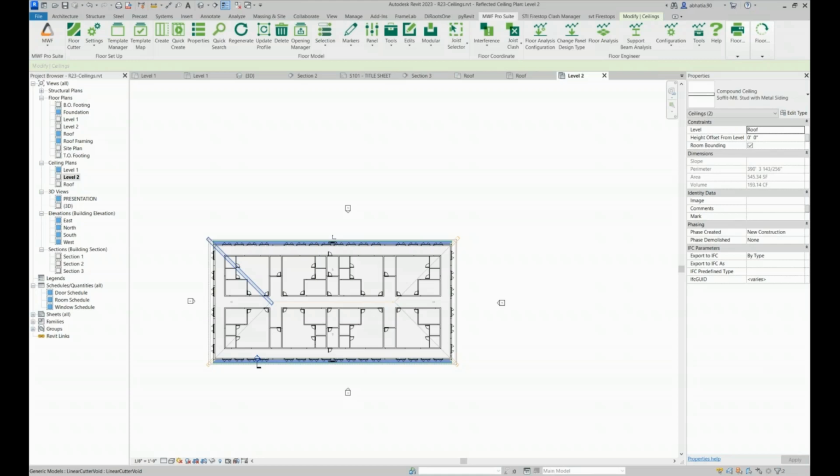You can use the T grid profile as your joists as well, but if you need the string for the grid to show up for your coordination and things like that, make sure you have a repeating profile or a detail line or model line that places that little line,